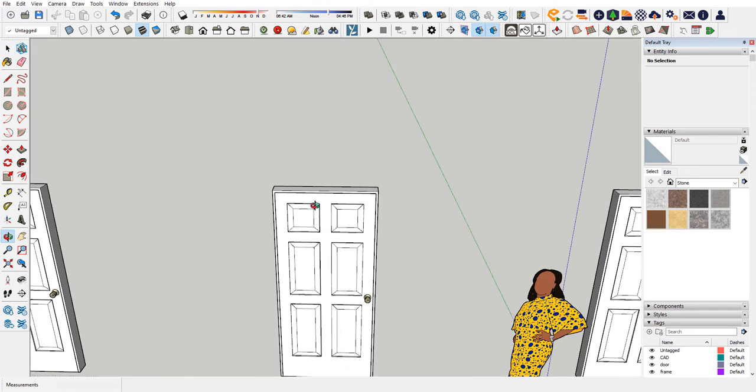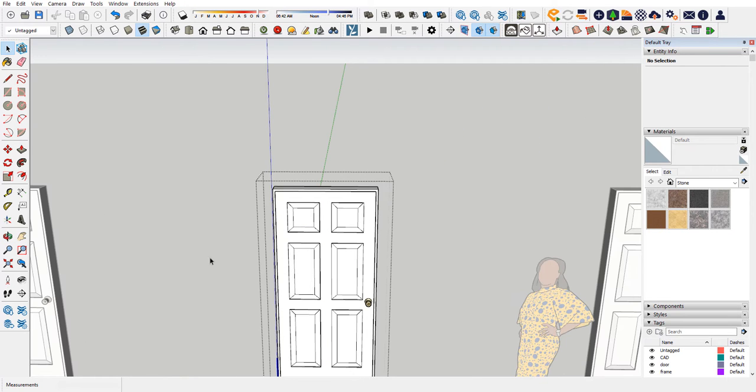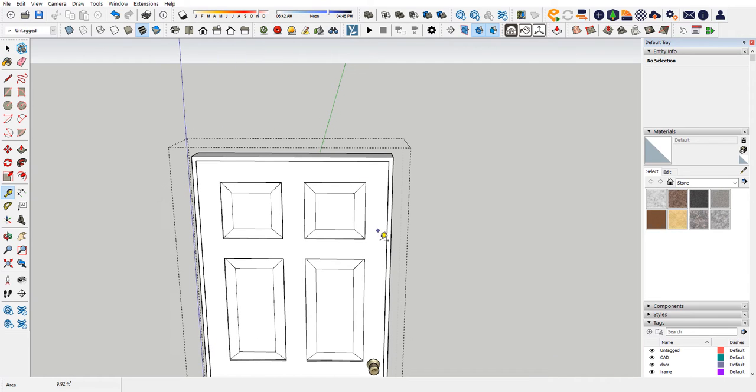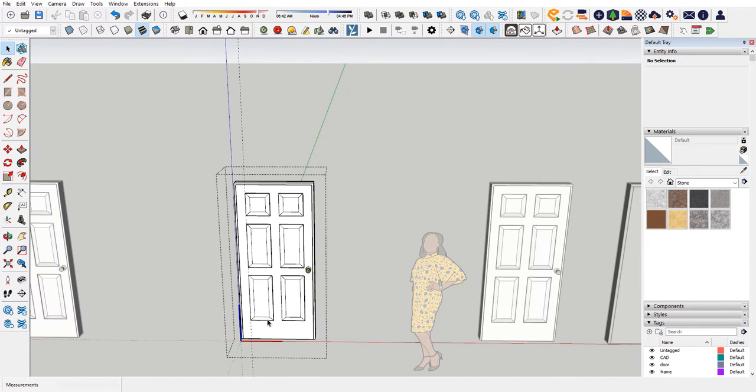All right. So I'm going to go ahead and double click. Let's make this door a little narrower. Let's make this door a 2'6" door. So T for tape measure. Click here, come across the surface, type in 2'6", enter. And so that door has to be that narrow.